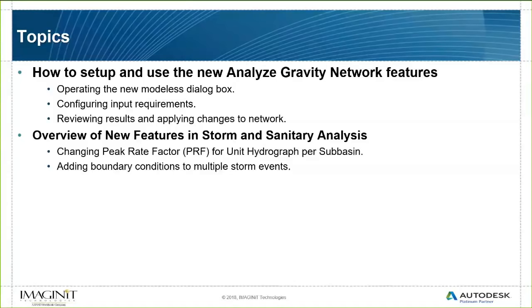I can also preview what it proposes to do, not only in tabular form, but I can also see it on my profile view. Whereas in times past you would give it the features, run it, it would give you the results, and then you'd have to go through and figure out if you want to keep them or not. I can see a preview now. I can still work in the drawing, and I can make decisions as to whether I want to keep the results or not, go back, change some variables, and then run the analysis again.